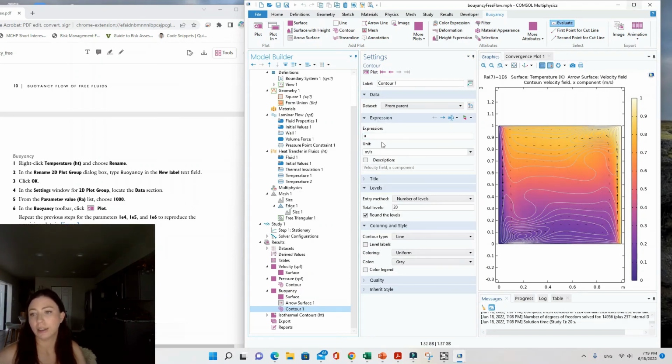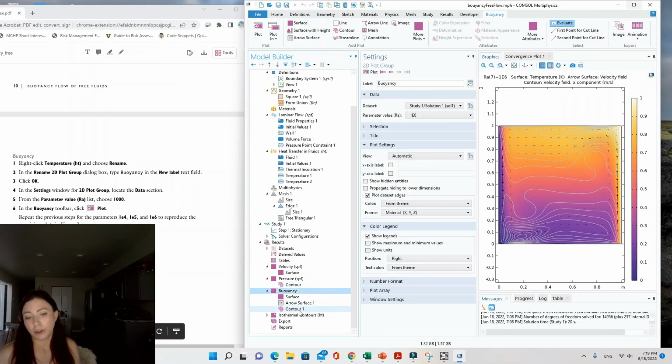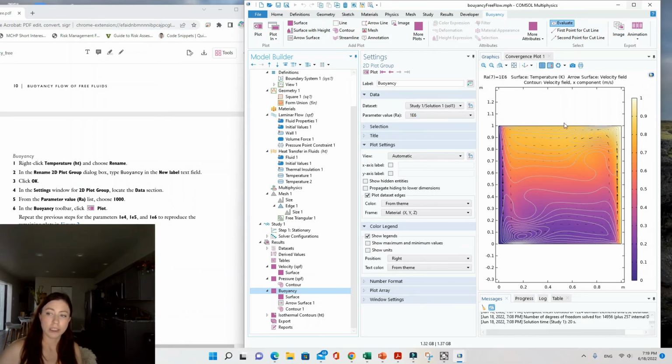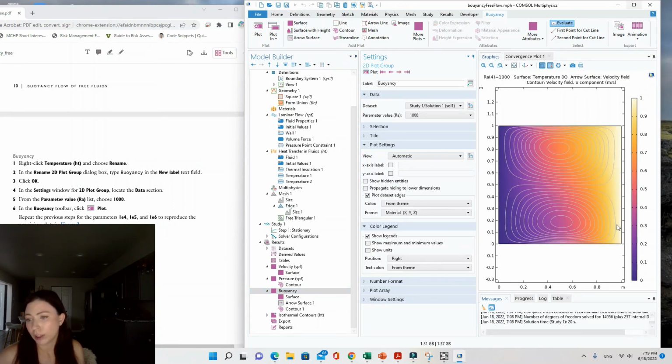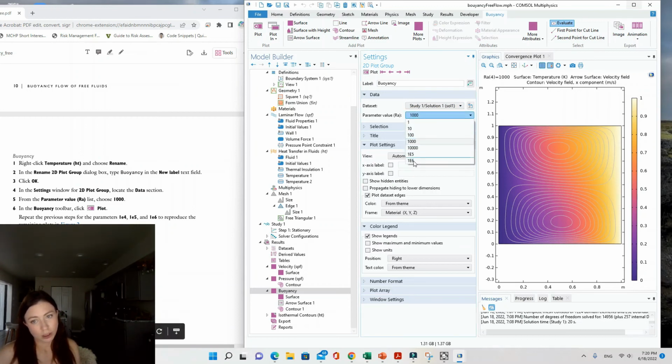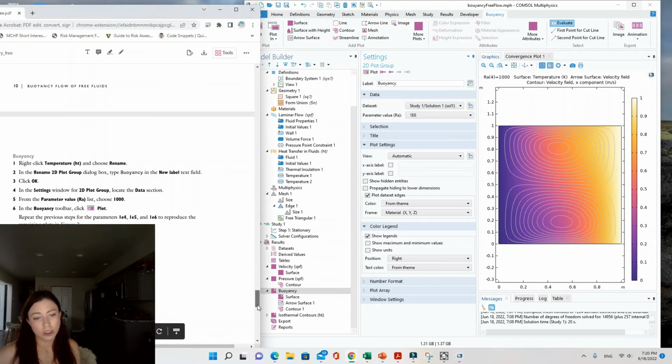So those gray lines are representing the X component of velocity. So as we're changing this Rayleigh parameter value, we can see how the X component of the velocity of the fluid changes. So if this is the X direction, and we already said the velocity in the Y direction is very high along the left and right boundaries, since it's the high temperature and low temperature, we can see the effect in the other coordinate, the X coordinate, by changing from very high values to, compared with the low value, it's sort of a, you've got two eddies, I guess you would call this. So you've got sort of contours on the top half and bottom half at lower Rayleigh values, given the same temperature delta, right?